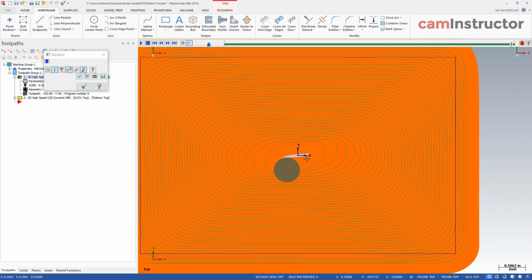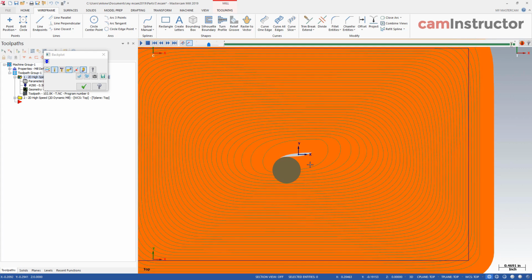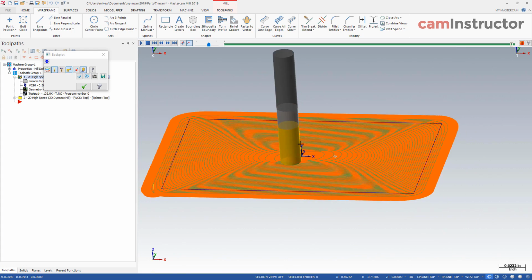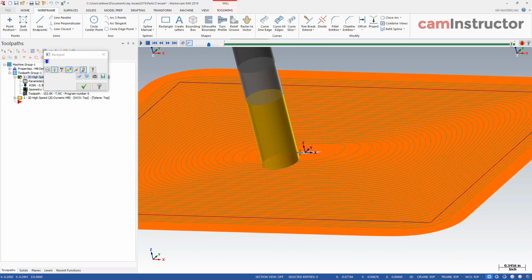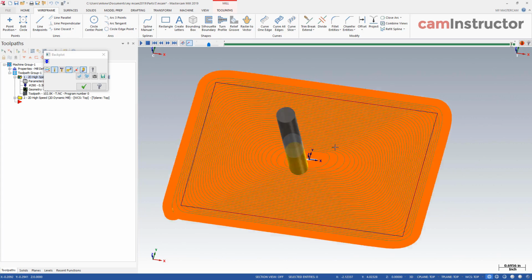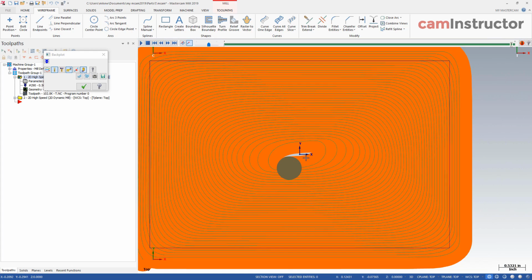So maybe if you have something that's very, very soft and you're doing a very, very light cut over, you might want to either increase your step over and reduce your step down so that you get a stiffer middle section here and you're cutting more at once, to prevent this piece from bending over and deflecting and taking out your end mill. So that's a word of caution about what can happen at this part of the toolpath. But yes, everything else that you're seeing happen in these toolpaths is by design, it is on purpose, and it is to maintain that tool engagement angle.